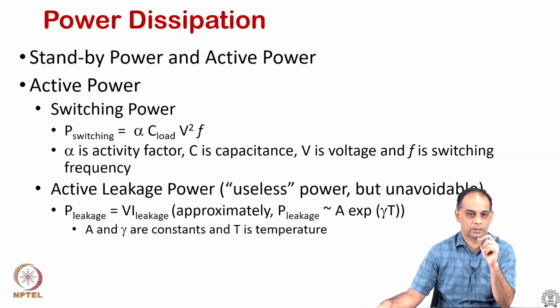That is typically called the switching power, and this is the main component that we try to dissipate as heat. This alpha C V squared F power is primarily occurring because of discharge of the capacitance in these circuits. These transistors are implemented as switches and valves in the processors or any device.